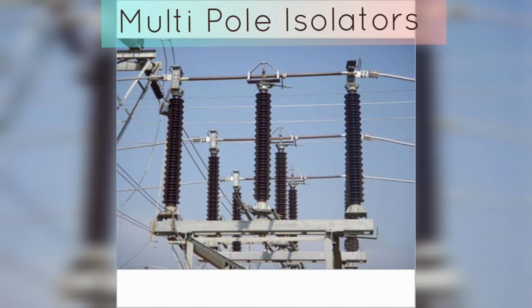A multi-pole isolator is an electrical switch that is used to disconnect or isolate a specific part of an electrical circuit from the rest of the circuit. It is designed to break the electrical connection between the source of power and the load that it is connected to. The term multi-pole refers to the fact that this type of isolator has multiple poles or contacts, which means it can disconnect multiple circuits simultaneously.